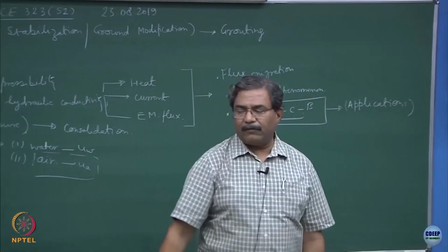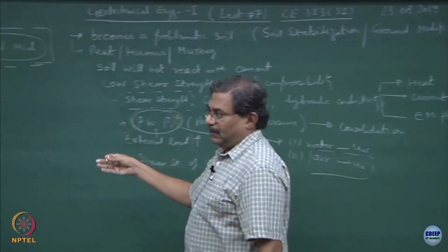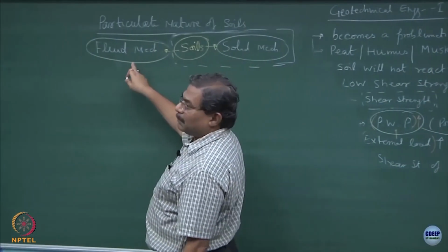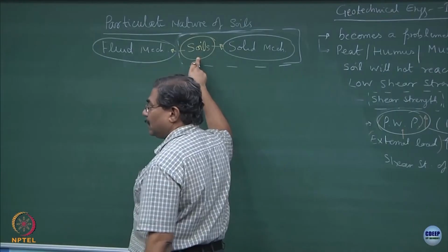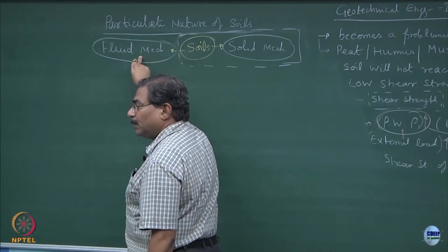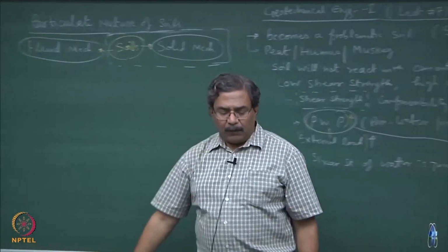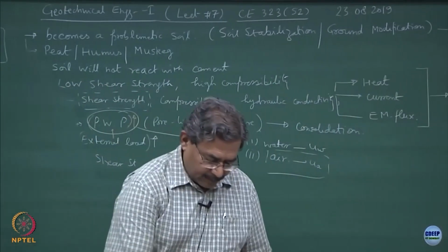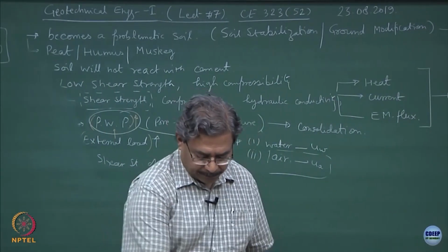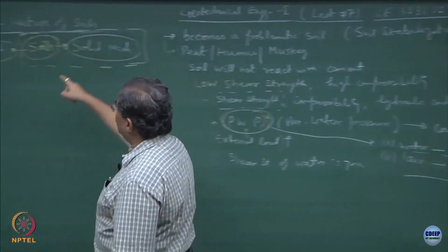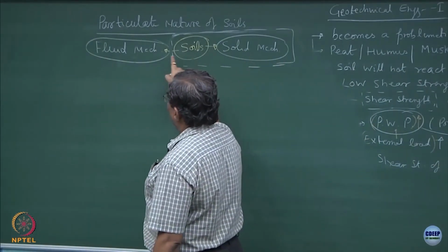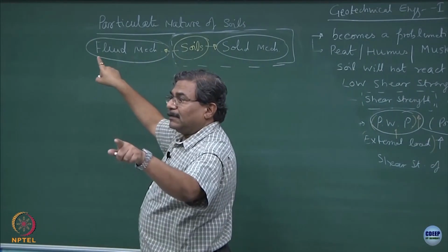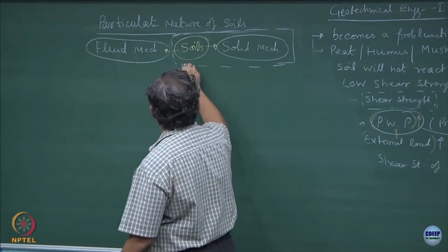I gave you an example last time, dredging. Those of you who are going to be experts in dredging would make a slurry of the soils which is going to be in the fluid state. So, I hope you can realize this interesting behavior of soils. The material you can use the way you want. What is controlling these two transitions? The moisture content.